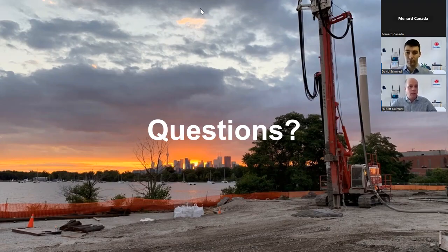There are ways to mitigate that risk of instability, but of course we need to be very cautious. I don't have a specific answer; it has to be adapted project to project. You cannot just use dynamic compaction blindly at the toe of a berm to fix an issue. You need to make sure that you understand the global stability and also the effect that you might have on the structure. So for that, we need to go on a case-by-case basis.